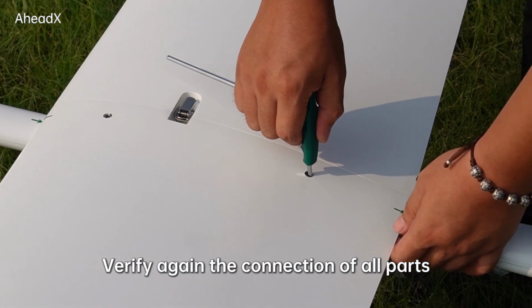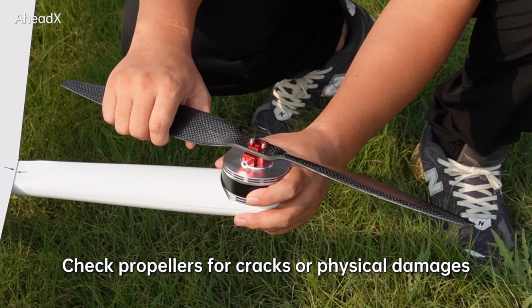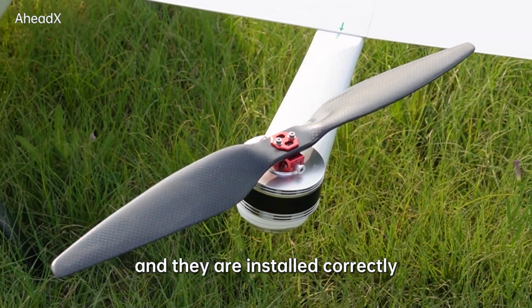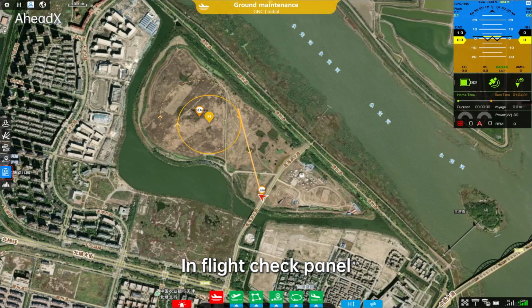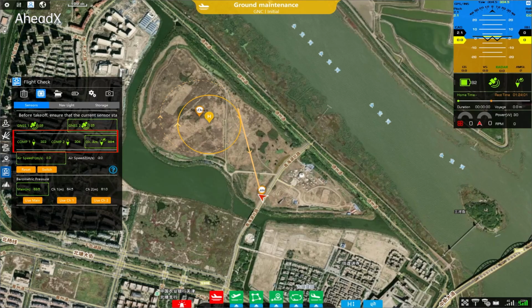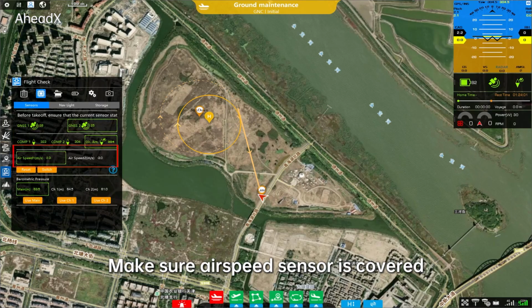Verify again the connection of all parts. Check propellers for cracks or physical damages. And they are installed correctly. In Flight Check panel, Sensors check. Make sure we have good satellites. Check the compass status. Make sure airspeed sensor is covered.